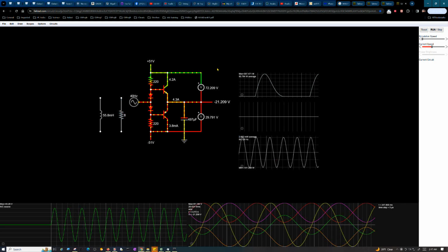So that's why, with an inductive or capacitive load, you often see warnings on lamp dimmers for your wall, to control your room lighting, saying not designed for inductive loads, meaning don't try to drive ceiling fans with them. Because of the inductance of the motor, it can cause the triac in there to overheat, because it's having to eat all that power coming from the stray inductance in the motor, and that can exceed its limits quite easily.